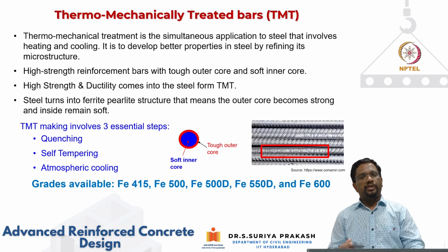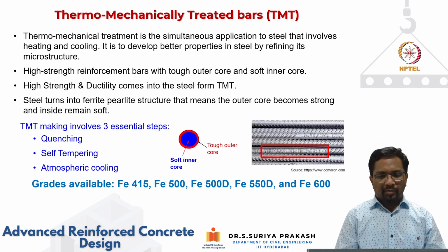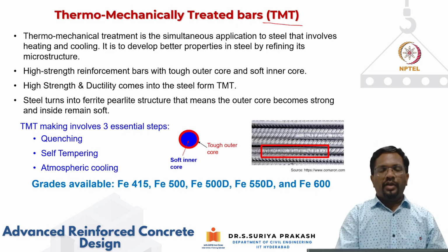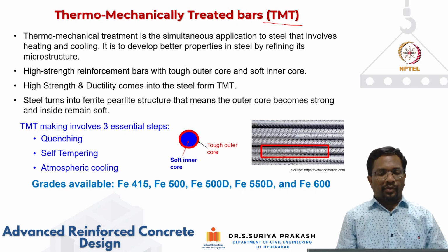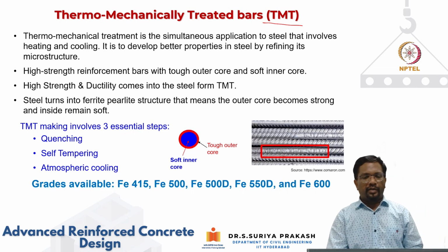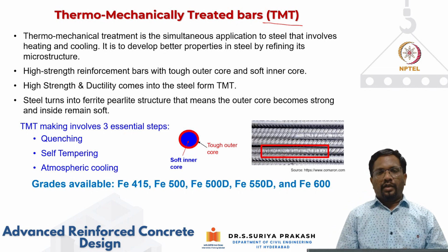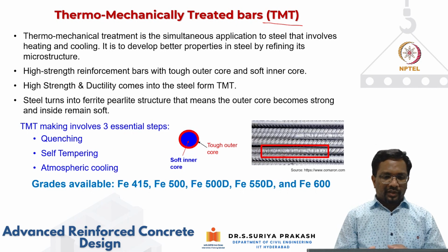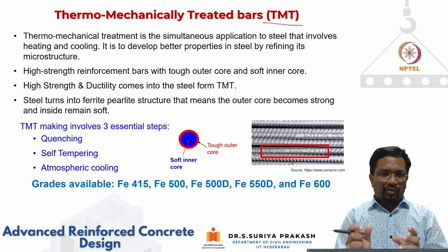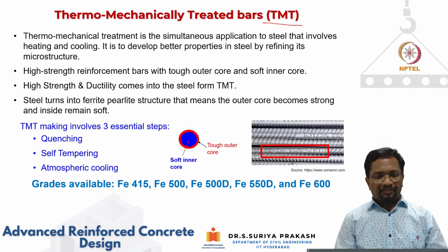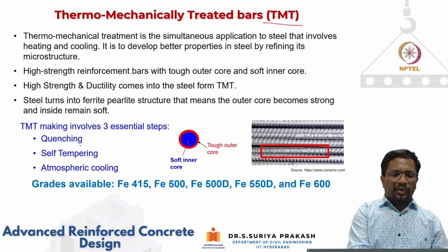Nowadays, what is commonly available in the market are what are called thermomechanically treated bars, also called in short form TMT rebars. And what is this TMT process? Thermomechanical treatment is actually simultaneous application to steel of heating and cooling. Basically, what we do is we heat it and cool it suddenly over a very short period of time. That's what they call quenching.